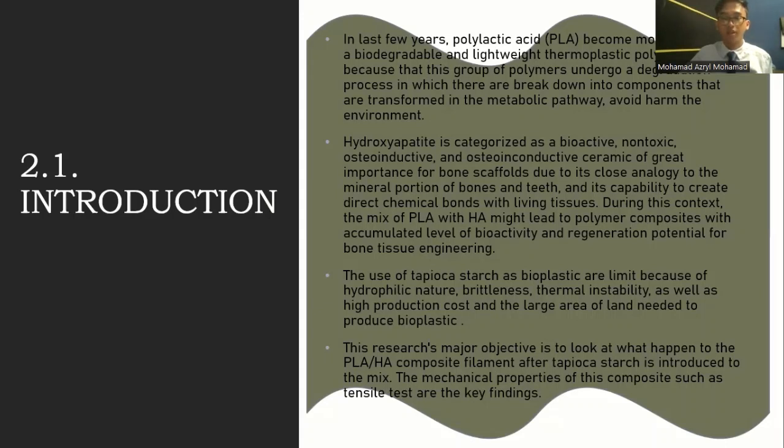The use of tapioca starch as bioplastic is limited because of its hydrophilic nature, brittleness, thermal instability, as well as a high production cost and large area of land needed to produce bioplastic. This research's major objective is to look at what happened to the PLA-HA composite filament after tapioca starch is introduced to the mix. The mechanical properties of these composites such as tensile are the key of the finding.